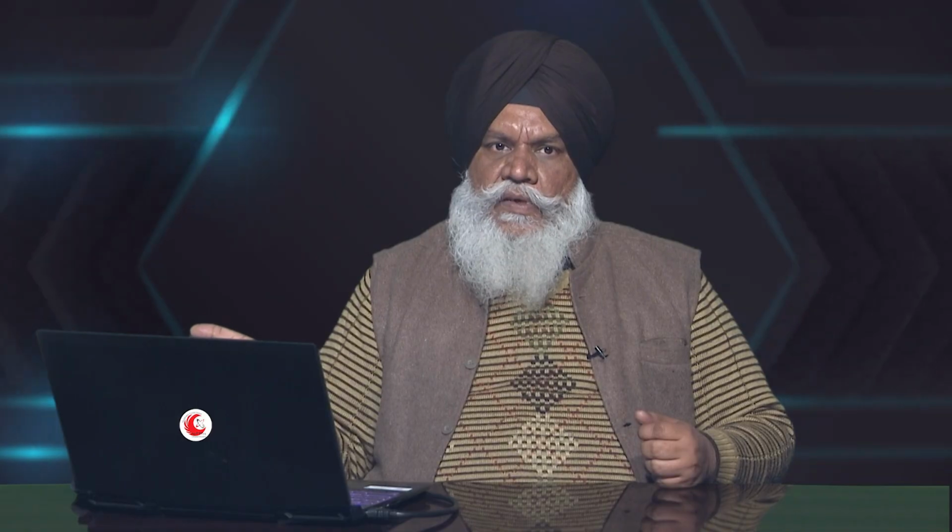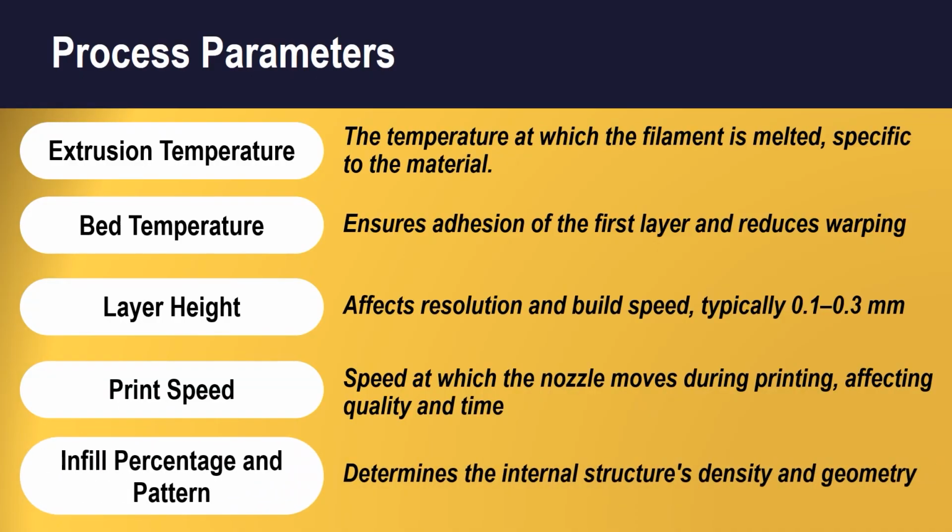If print speed is high, the production time will be lowered, but sometimes the solidification rate has to be correlated. Similarly, infill percentage and pattern. It basically determines the internal structure, density, and the geometry. If I put a high infill percentage, I will have a more solid part. So I have an option like putting it at 10%, 20%, up to 100%.